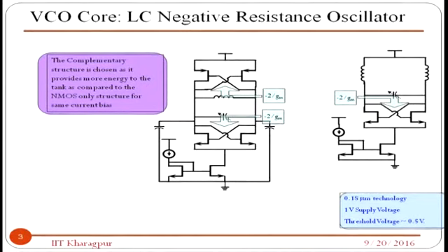within the system. So, basically the cross coupled pair here is to have a negative impedance with respect to the tank circuit. That is the reason why you are using a cross coupled pair. And secondly, you can utilize only an N coupled pair, that is 2 N type transistors cross coupled. In that case, your impedance is 2 by Gm.